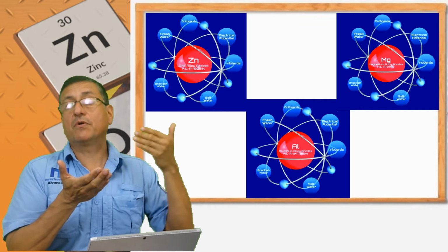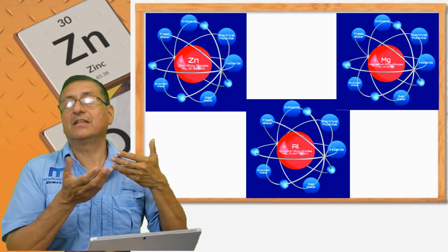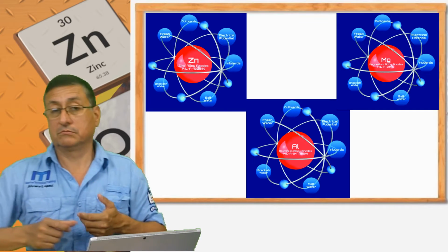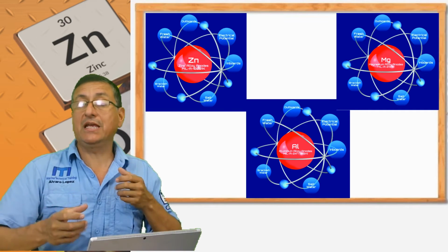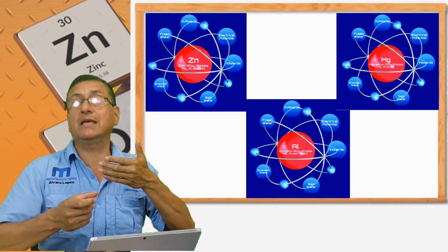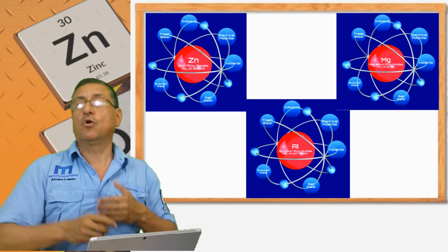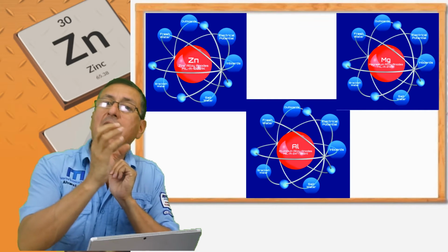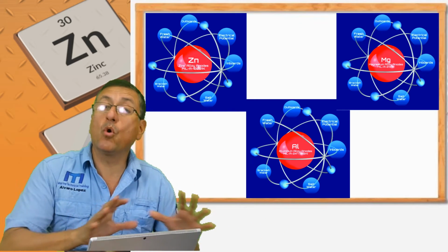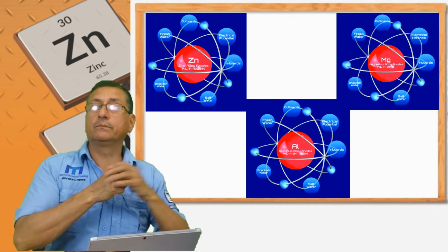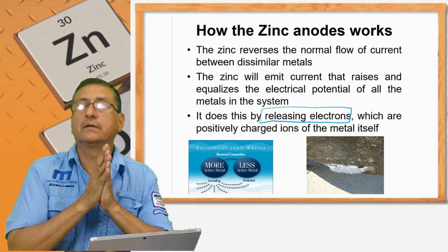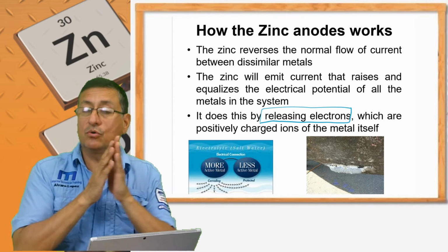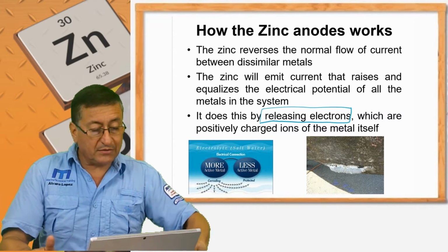Depending on the water and the type of material in the hull, the differential potential is better with one anode or better with the other anode. I have a better difference in level of energy with this sacrificial anode, or with this, or with this. This is the secret: select the appropriate sacrificial anode according to the water and according to the material of the hull. Select the appropriate sacrificial anode according to those factors. And we are going to check right now what that means.